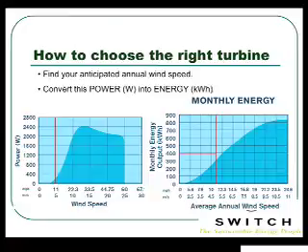Well, what does that work out to? Remember I said that there's seasonal variabilities, and you have to look over the year. So on a monthly basis, if we're out at about 5 meters a second, then what happens here? I think this was shifted one way. I believe it was over here where the line intersects. At about 5.5 meters a second, you can anticipate about 400 kilowatt hours a month out of that. Sure, there's going to be times when you're going to generate a lot more. There'll be times when you look up and the turbine won't be spinning. But that's on average what you can expect.